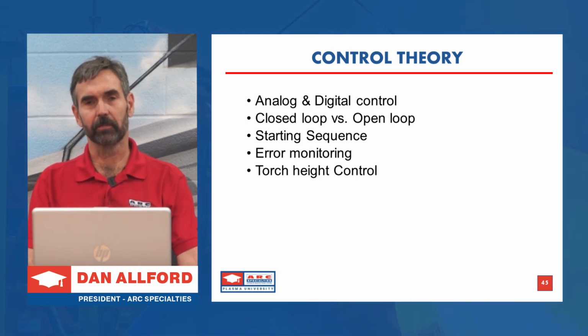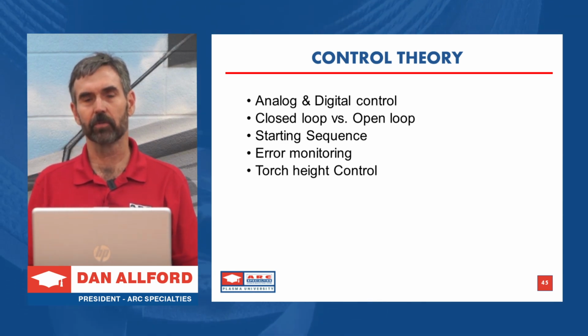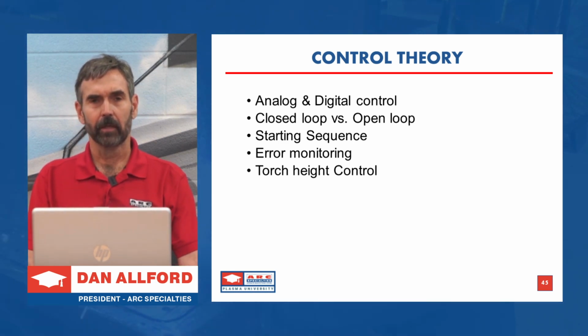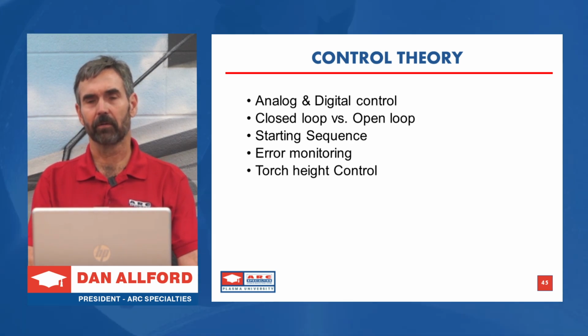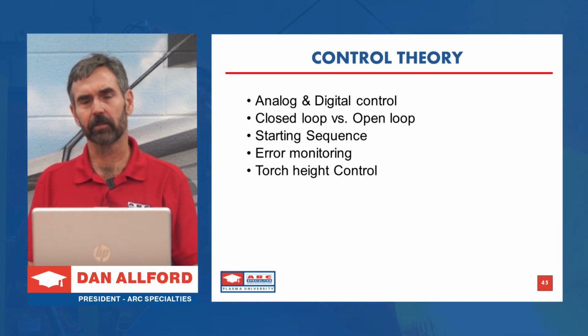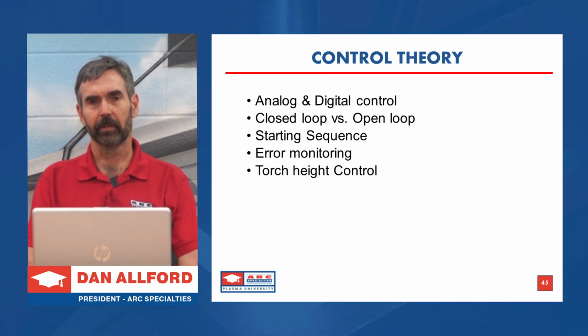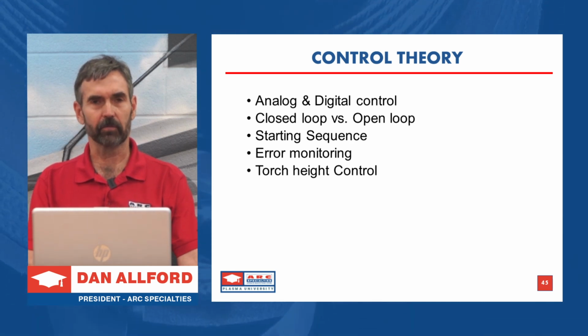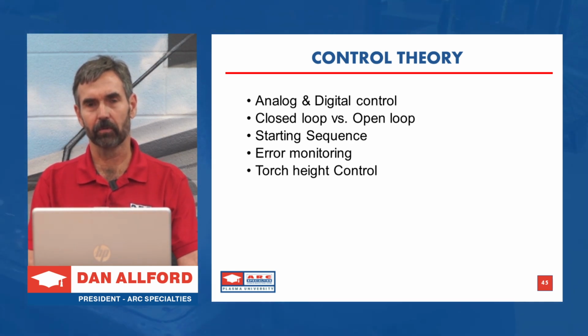And then once we're finally at peak current, we continue to pulse probably at 2 or 3 hertz, that's 2 or 3 pulses per second. And typically our peak is twice as much as our background. So we reduce our main current by a factor of 2 on the background period, and we're pulsing back and forth just to reduce the whole overall heat input.